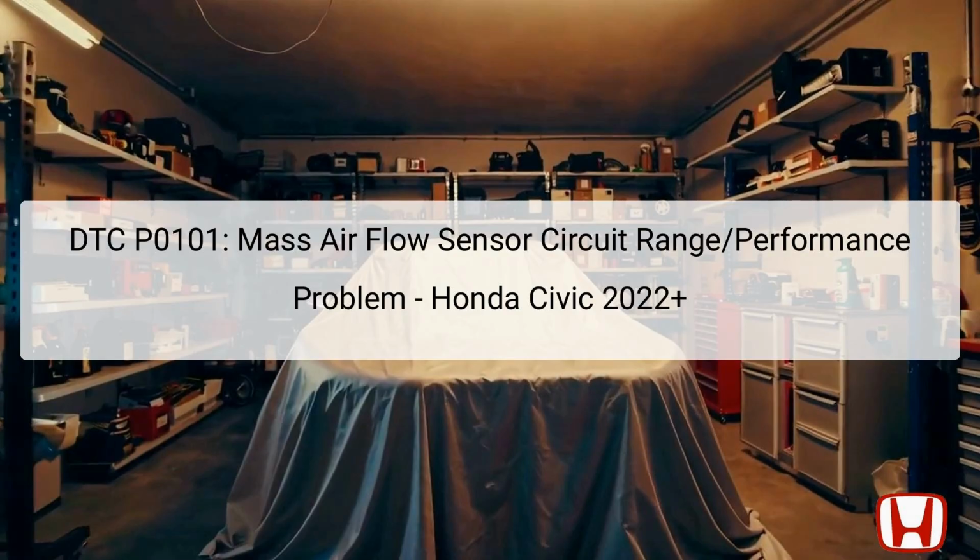A problem arises when the MAF sensor output frequency falls outside of an expected range, prompting the PCM to store this diagnostic trouble code. Understanding what triggers this code can help technicians conduct efficient troubleshooting to maintain the performance and emission standards of Honda Civics. Addressing P0101 promptly is crucial to prevent further complications in engine performance and efficiency.